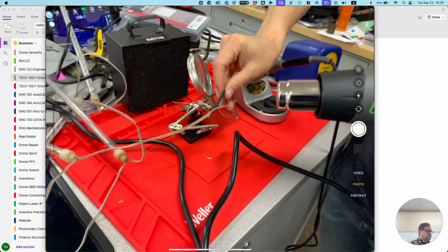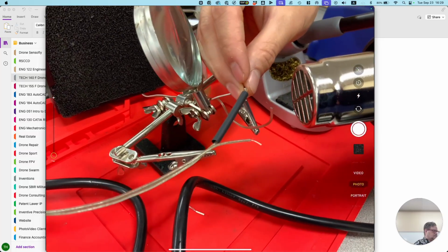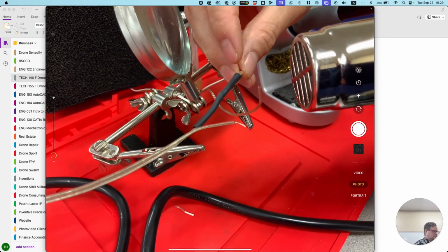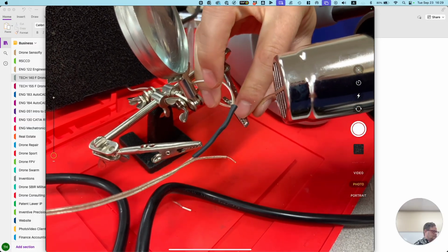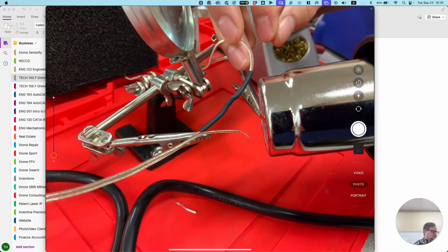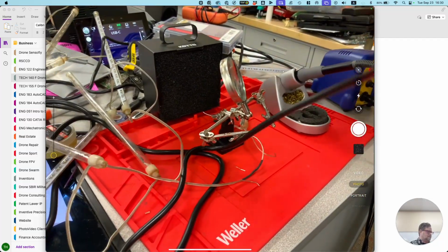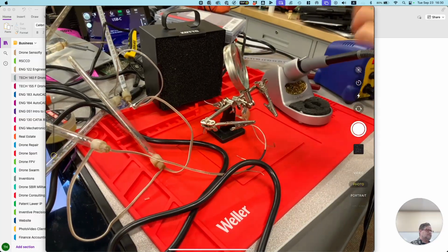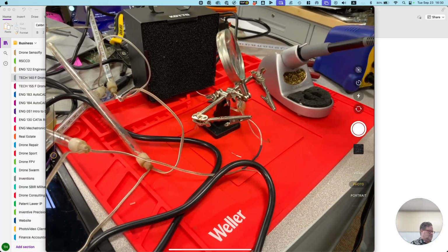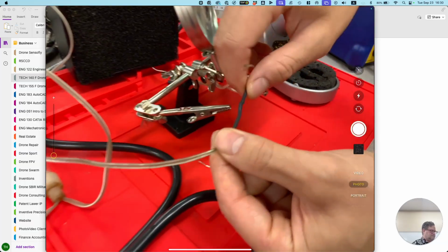So I'm just gonna set it to one of them, and if you look closely, it's going to start to shrink down. Okay. I can see the constriction point where it was soldered. There it is. Do you know what the temperature is to start making the heat shrink shrink? Is it pretty low heat? It's pretty low heat. It's going to be lower than the soldering. So you're not going to reflow if that was your concern. Now it's on there, you see? It's not slipping around anymore.